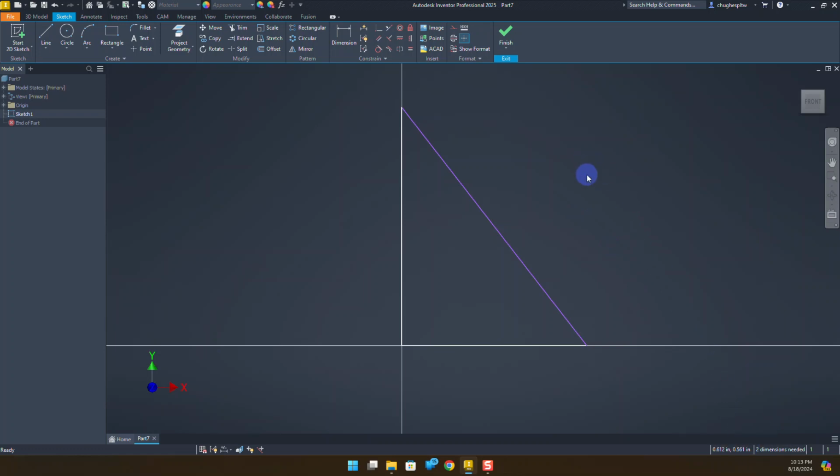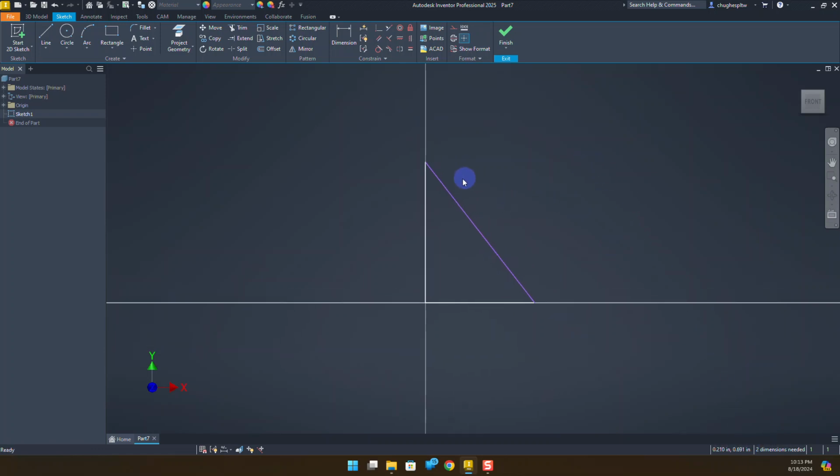I need 2 dimensions for this sketch, and I can see that this one line here I can actually play around with and manipulate the size of the triangle. You can also select dimension up here, but you can also select the D key on the keyboard to run it. Notice how it's highlighted up here. When it's highlighted, that means we're running that command. So I'm going to select the height here. This is going to be a 1 inch even.